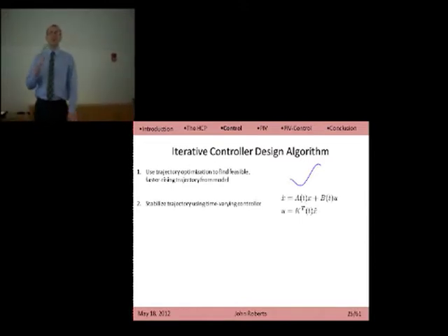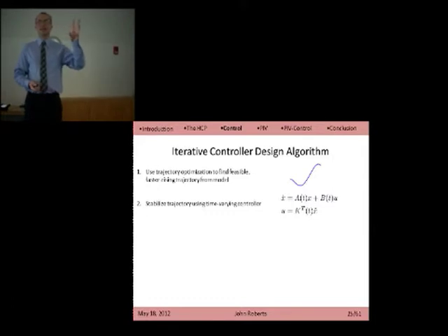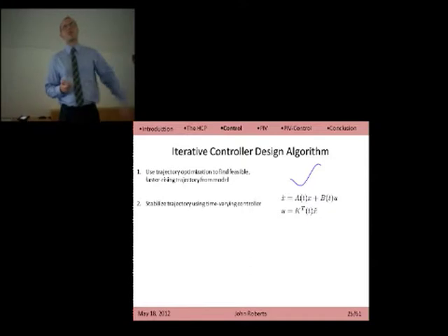We stabilize the trajectory with a time-varying linear controller. So the same LQR approach we used previously, we'll use in this one. But because the system is changing significantly, we'll make it a function of time, not just a fixed control gain. This will deal with the fact that the trajectory is not ideal, so the system's not perfectly correct. And this will give us some robustness to the errors in our model, and also make sure that we don't just run an open loop trajectory that does something irresponsible.